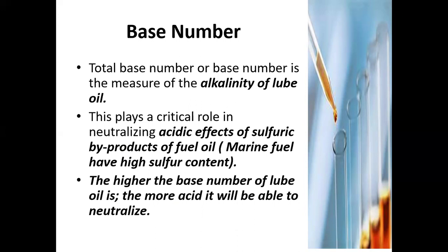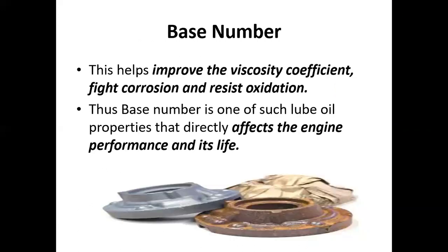The higher the base number of the lube oil, the more acid it will be able to neutralize. So as much as possible, we want a higher base number so that we have a higher amount of acid to be neutralized in our system. This helps improve the viscosity coefficient, fight corrosion, and resist oxidation. Thus, base number is one of those lube oil properties that directly affects engine performance and its life.